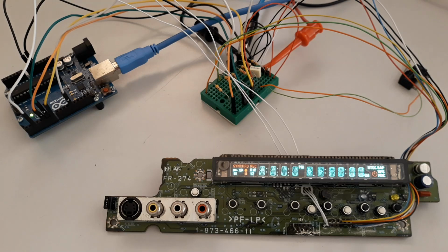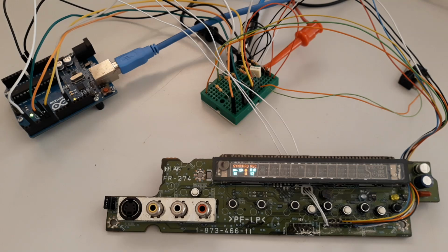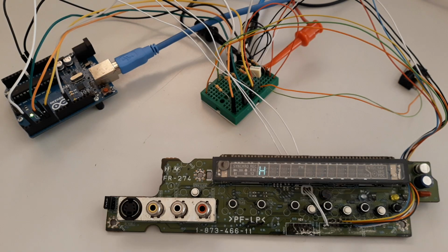This driver allows the control of 4 external LEDs. In this panel, only 2 are used, port LED 2 and port LED 3. These ports normally provide a negative voltage when they are in the on state. This means that we need to connect the diode anode to a VCC through a resistor, of course, in order to turn it on or off by applying 0 volts to the LED port.